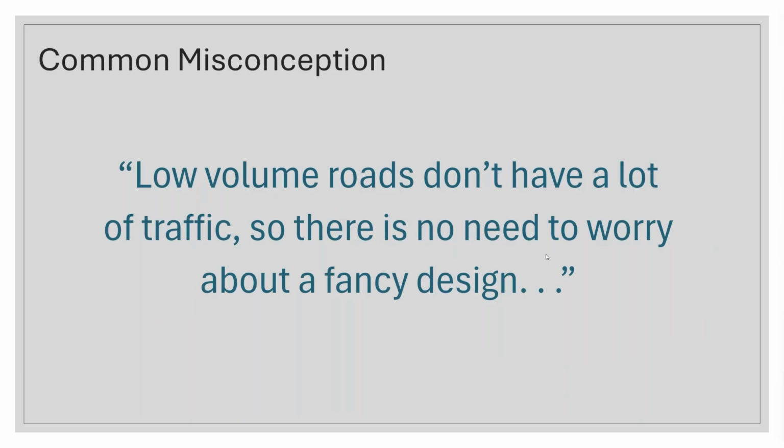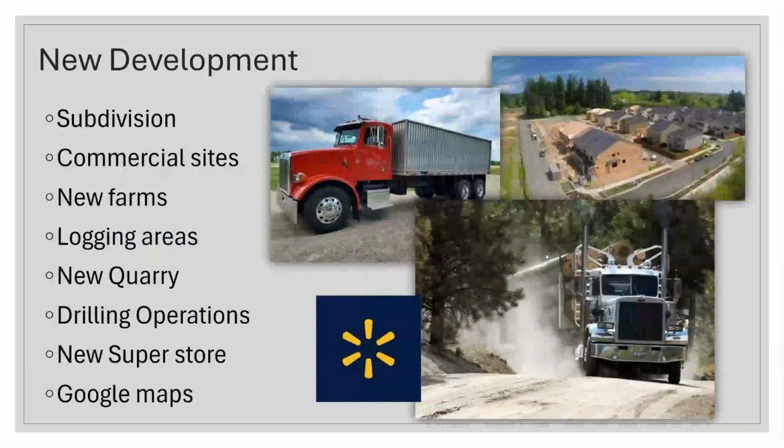And when we start looking at pavement design, even mix design for asphalt, how do we put the components of aggregate and asphalt together? Some of your design standards are based on how much traffic you have, and it will be in terms of ESALs. And it goes from 0.3 million ESALs to 10 million up to 30 million and more. When you start looking at city streets, you don't have those giant numbers to think about. It's not that much. So it makes you feel like, well, we don't have to do any of that fancy stuff. We'll be okay.